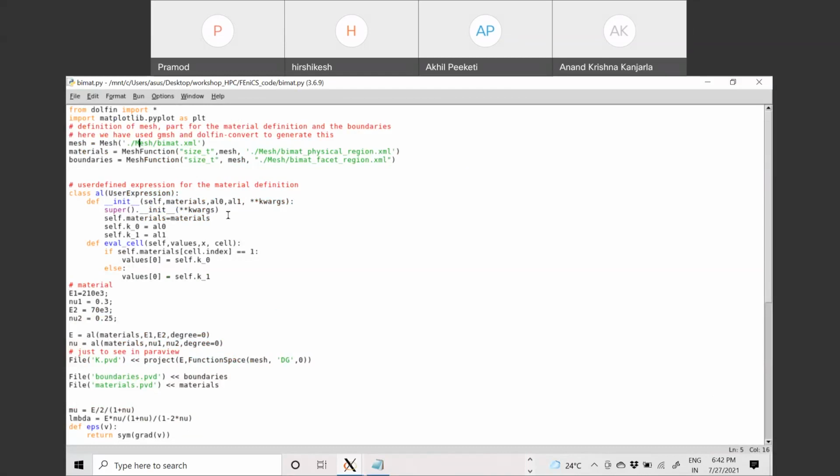In the same way, doing the material discontinuity problem, like you have a two-phase composite, let's say, or for that matter, functionally graded materials, in that case the weak form stays and only the material properties change. So implementing that is quite trivial. You need not model again or anything. Just in a mesh, specify in the code where you want to use, let's say, E1, Young's modulus of material 1, and E2, Young's modulus of material 2. Once we do that, everything else remains the same.